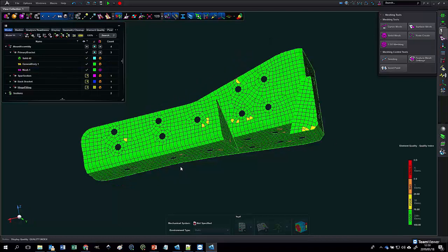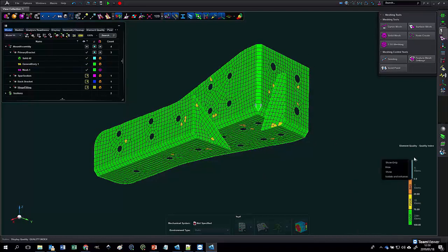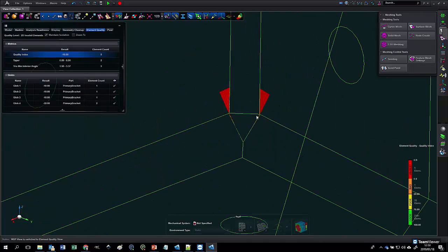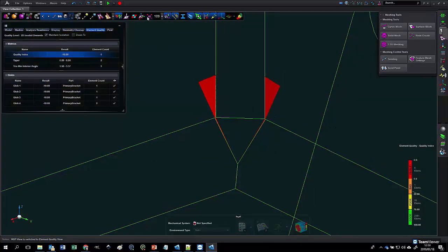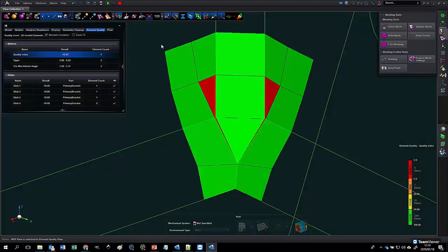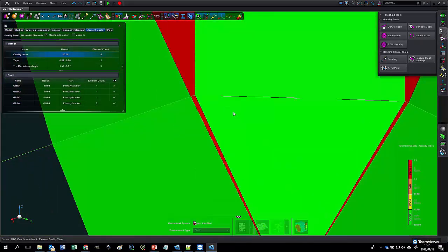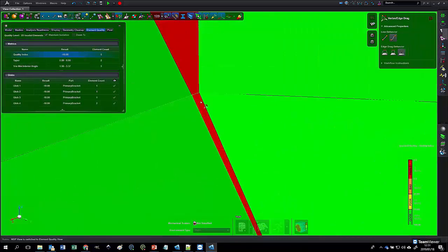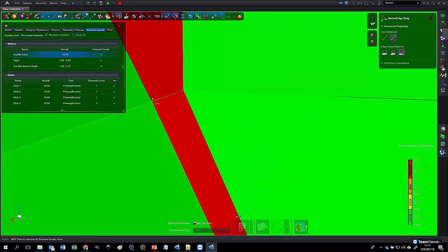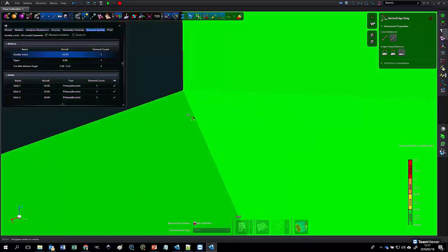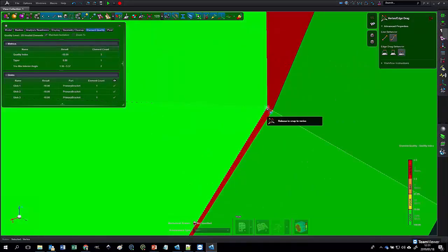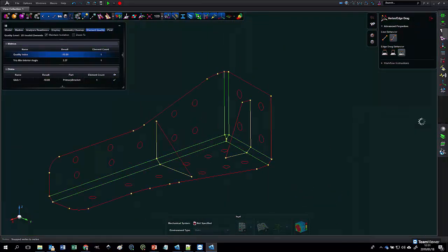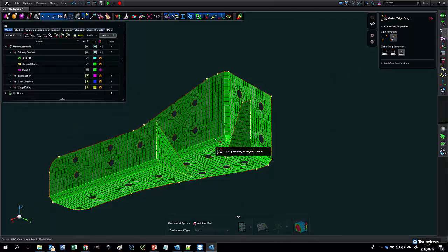And to find them, you can either visually look for them, or in large models that becomes quite difficult. And then you choose the right-click and isolate and enhance option. And it automatically shows you that there were problems over here with the geometry. And you can add some elements by growing the mesh. And if you zoom in closely, you can see, oh, wait a minute, there were some few edges left that didn't clean up so nicely. So we can fix this quite quickly by simply dragging the vertices of the geometry, and our mesh updates along with it.